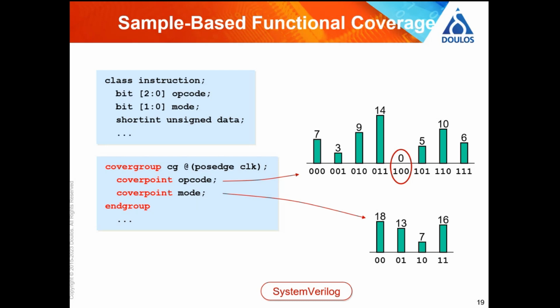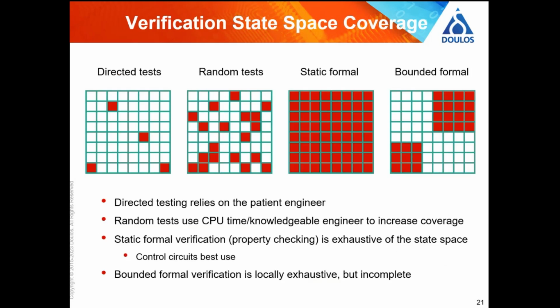So, if the design really were a CPU, then we do want to check that we've tested all of the opcodes. And you wouldn't actually see a histogram like this in any EDA tool, but you think of histograms like this sort of conceptually, and the number of opcode 4s executed in any simulation is 0. We haven't tested opcode 4 properly then, have we? And so we need to then go back to our stimulus and find out why that's the case. Is our test bench wrong? Have we just not run the simulation for long enough? Whatever the reason is.